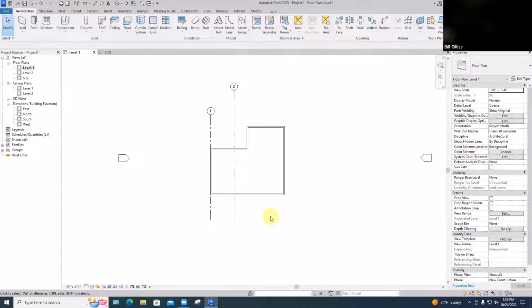And you want to be able to put furniture on that. It's not sitting on a level, it's sitting on the rake. So that's a case where you'd use a reference plane that can be at any orientation. And then the things that go into this organized space are elements, we'll say, of a couple of different kinds. The main ones are floors, walls, ceilings, and roofs. And those are hosted by a level, and hosted means move with and are part of.